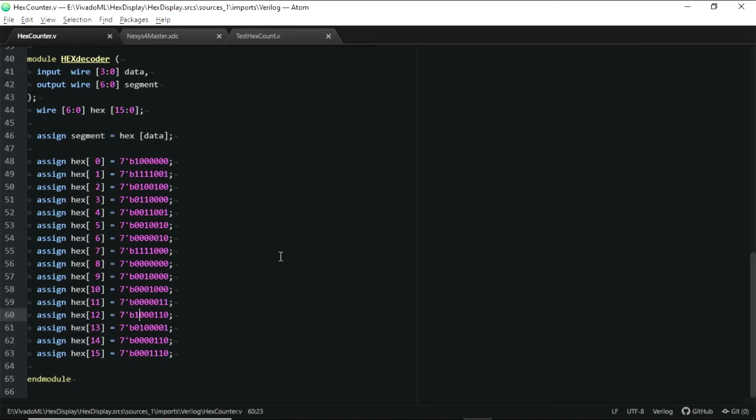That's the middle line, which is G. So it goes LED A, B, C, D, E, F, G. So it should look like C, but with the middle line included. And like I was trying to say before, this is a common anode, so all the bits are reversed from what you think they might be. That's where those problems come from.